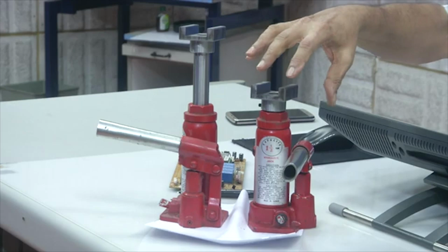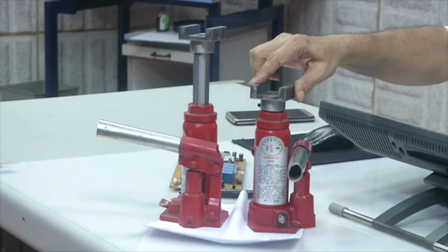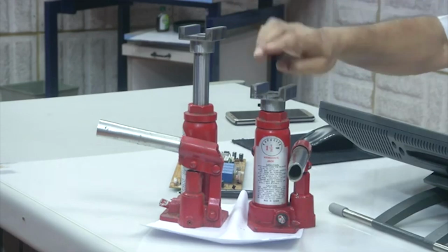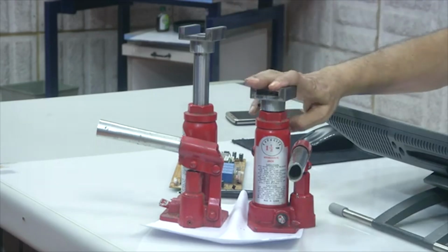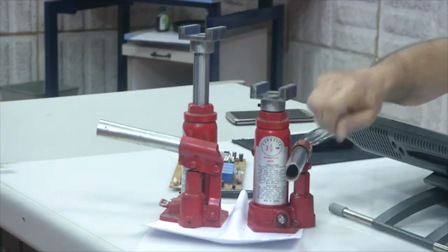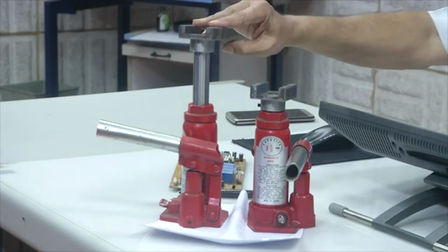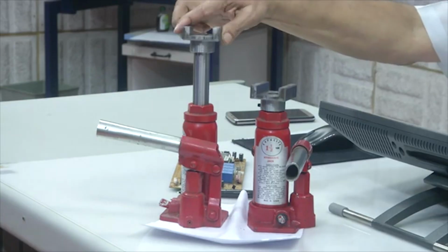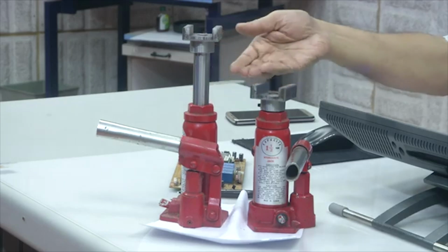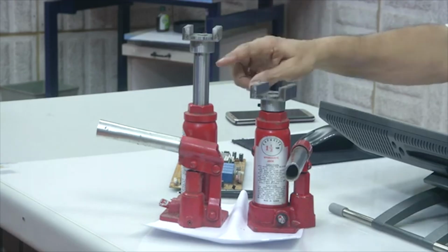Why this is shown is that this is the highest position and this is the smallest position, depending on the amount of raise you require. This is part of a vehicle chassis. It has been kept under an electric vehicle chassis, and then you jack it up. Once you operate this hydraulic jack, it has to be raised this much to make sure that this top member engages with the chassis member, and then lifts the wheels clear of the floor, and afterwards some other safety backup support is there.